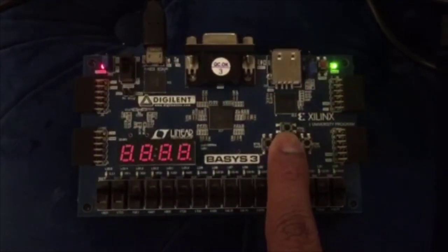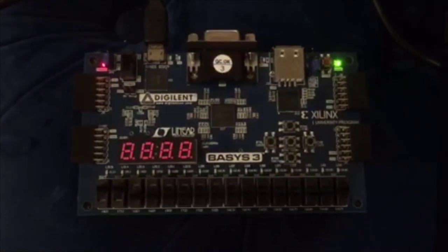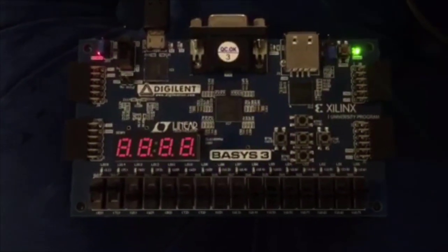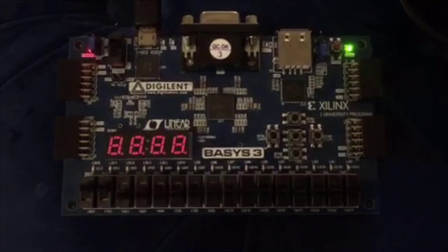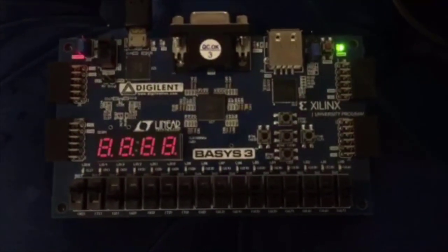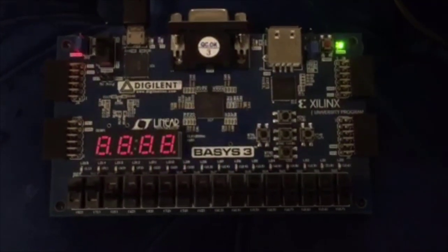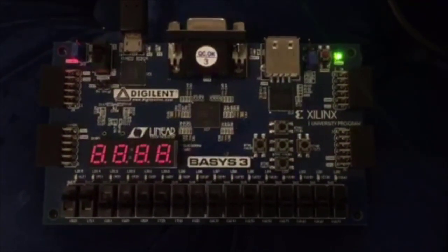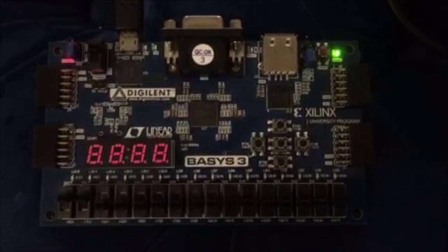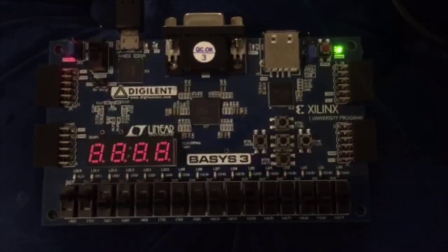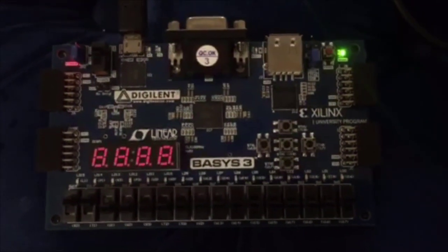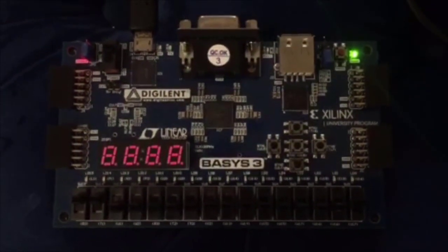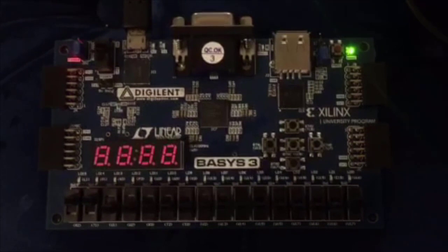Okay. So this is how the push buttons work, and it's important for us to do the debouncing because of the mechanical nature of these components. The signal swings between 0 and 1 before it gets stable, but if we can do some trick with it, basically waiting for a certain amount of time and then outputting the signal, coming up with a single output pulse, that is what debouncing does.